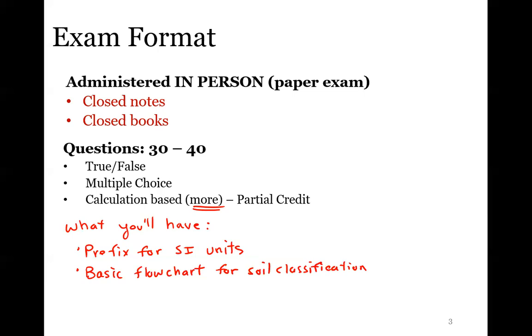So just to recap those, for USCS, if passing the 200 is greater than 50%, then that is a fine grain soil. The 200 sieve is really important.